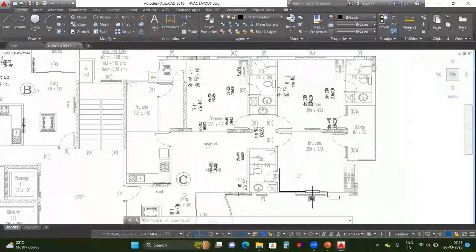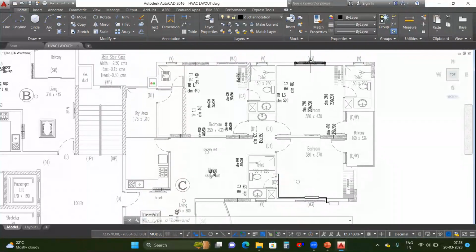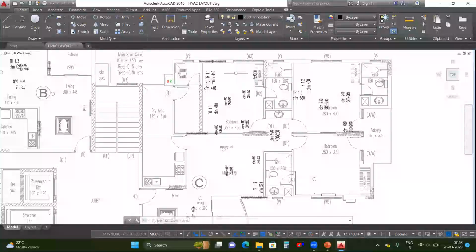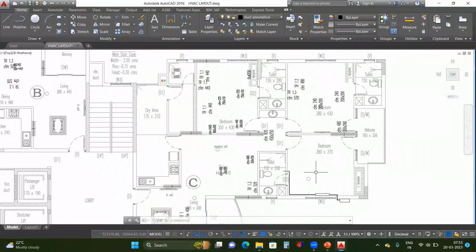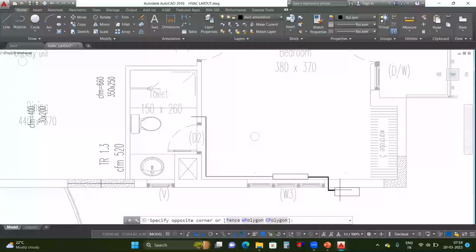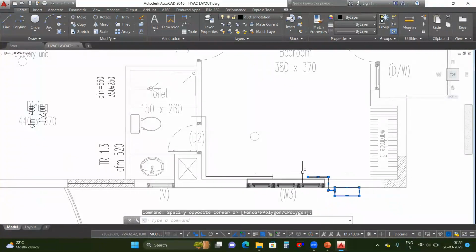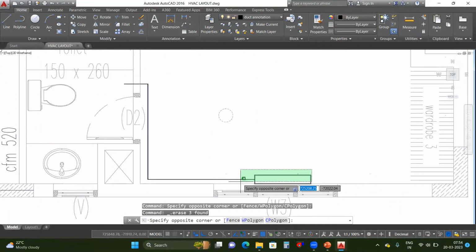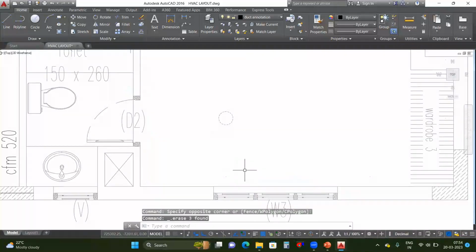So if you take these kind of split AC for the 4 rooms, here one indoor, one outdoor, here also one indoor, one outdoor, one indoor and outdoor. So here total how many indoors will be there? 4, and 4 outdoor will be there. So that is waste of investment of money, and also the operation cost is high. So okay, to avoid this, what we'll do, we will select the different unit. I will remove this. Okay.